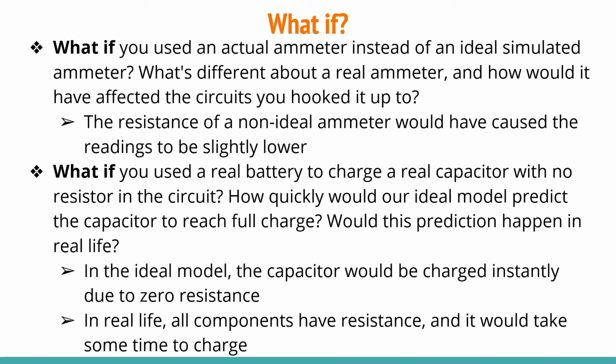Finally, what if I had used a real battery to charge a real capacitor with no resistor in the circuit? How long would the ideal model predict the capacitor would take to charge fully? Would this prediction happen in real life? In the ideal model, the capacitor would be charged instantaneously because there would be no resistance. However, in real life, all components have resistance and it would take some time for the capacitor to reach full charge.